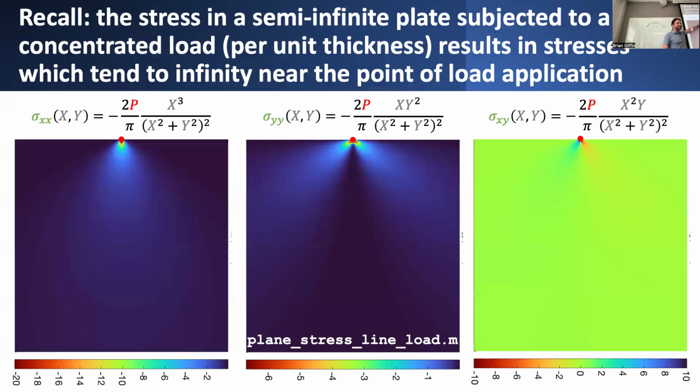Take a look at this image. We know that local to the point of application of some load, you're going to have very concentrated forces. But as you go further and further away from the load, things start to fan out or distribute out. So in reality, these loads coming from the building are not going to go straight down, obviously. According to this solution, they should really fan out and do something like this, right?